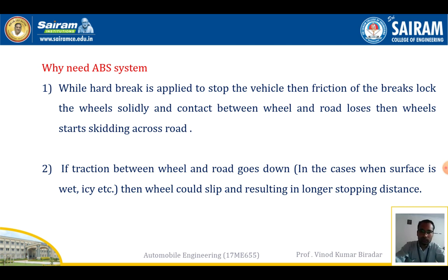This anti-lock braking system is used in almost all vehicles. When the friction or traction between the wheel and road goes down, the wheel could slip, resulting in a longer stopping distance. Even if the road is rough, uneven, uphill, or downhill, it will lock the wheel and stop the vehicle.